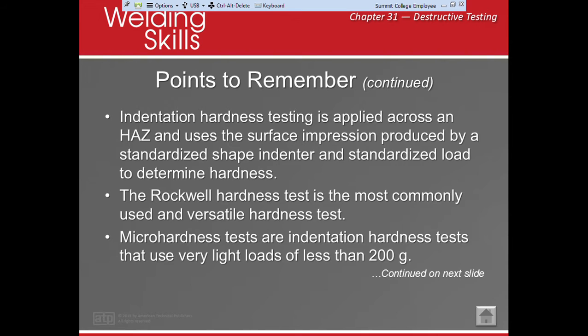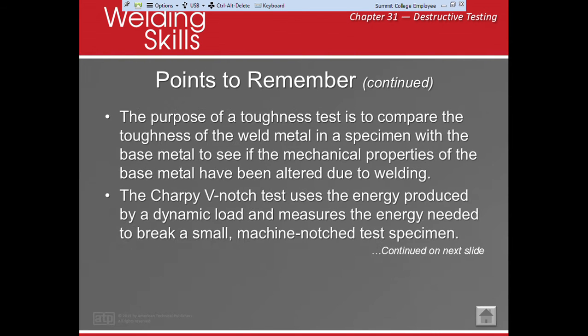All right, indentation hardness is applied across an area like the HAZ, and it uses the impression produced by the indenter to determine how hard it is. The Rockwell hardness test is the most commonly used and most versatile. Okay, remember that, Rockwell. Micro hardness test, micro, small, uses very light loads, less than 200 grams.